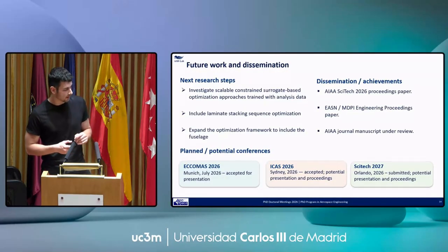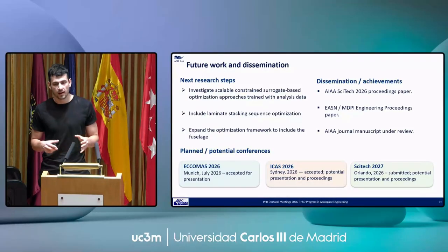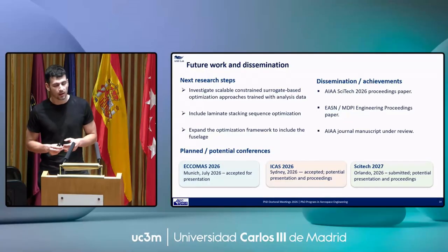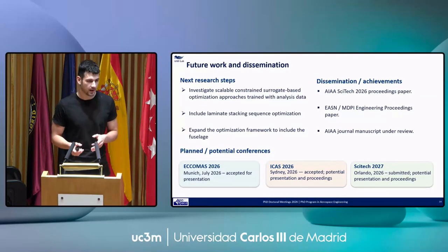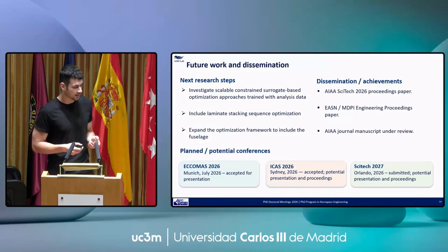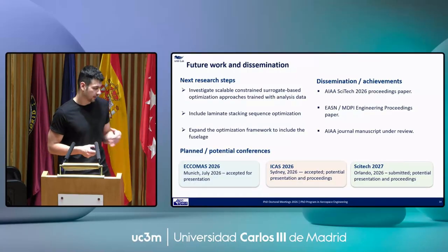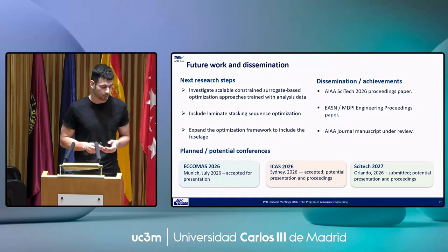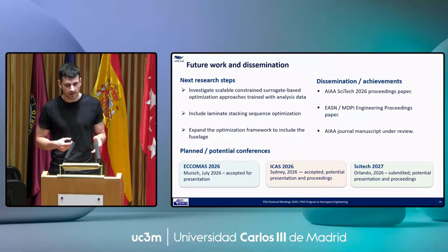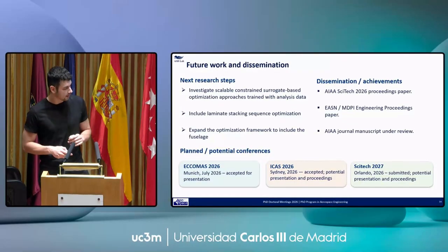For the next steps, I would like to investigate other formulations to solve the problem, which are, for example, scalable surrogate models or constrained Bayesian optimization, which will be trained on analysis data rather than sizing. I would like to include laminate stacking sequence, which is important, and potentially expand the framework to include the fuselage. You can also see some dissemination achievements and some planned conferences, but in principle, that's all.